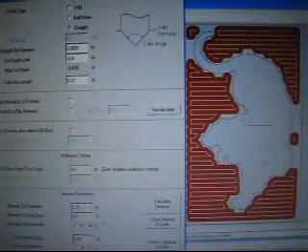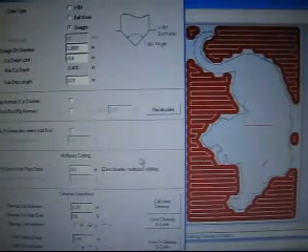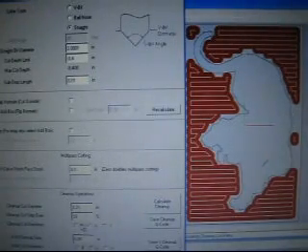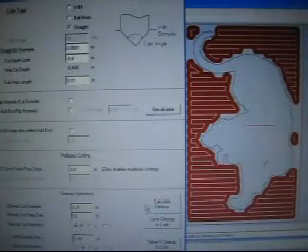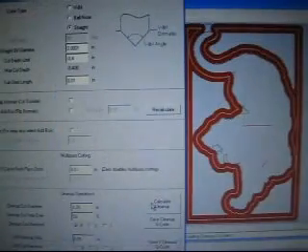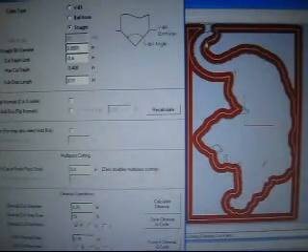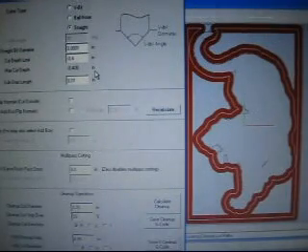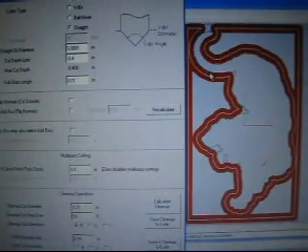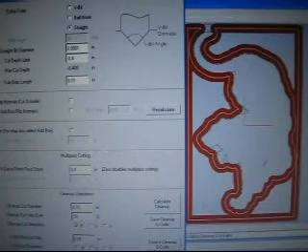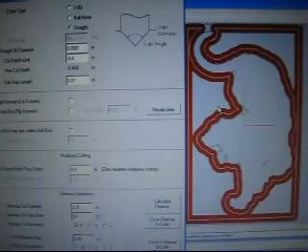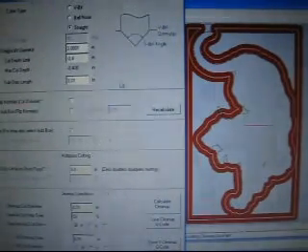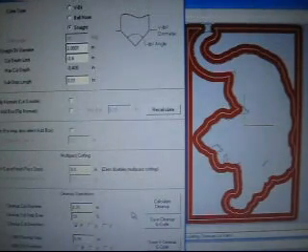We have more cleanup taking place. What I'm going to do is output this into 2 separate files. First in the X direction, and then I'm going to come back and go in the P, which stands for perimeter. So I'll calculate the cleanup at the perimeter, and you'll see we're getting pretty much exactly what we had before by using the top portion of this program. The only difference is there's a 1/10,000th of an inch gap around this thing, which is perfectly acceptable for wood. I don't have a problem with that at all. I'm just tricking the system into giving me a better cut.